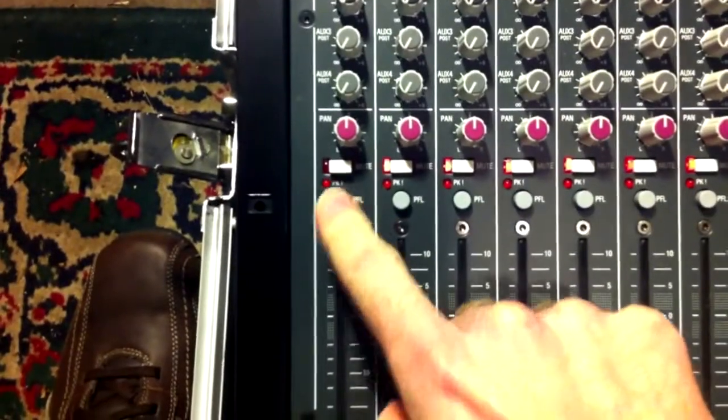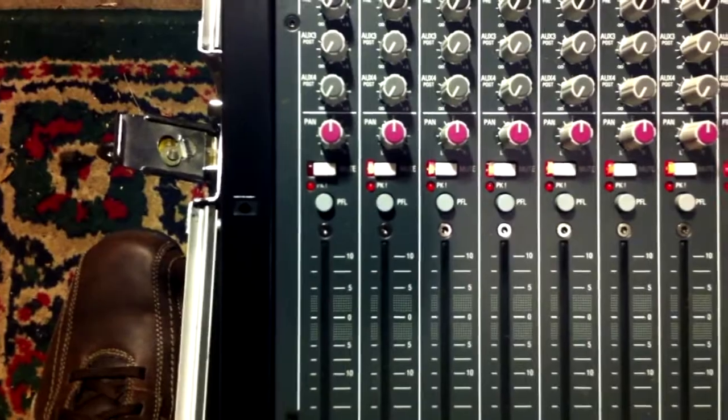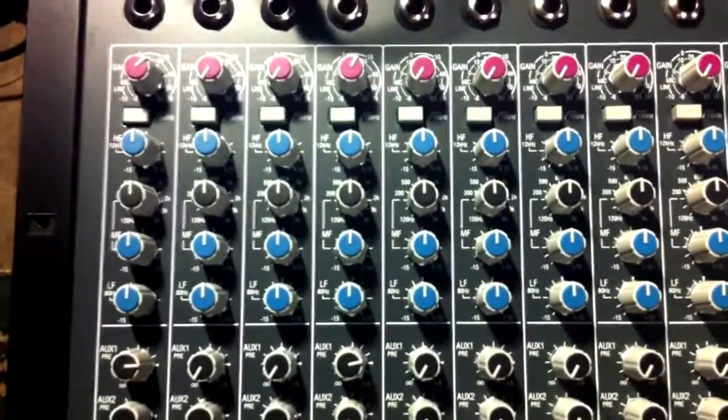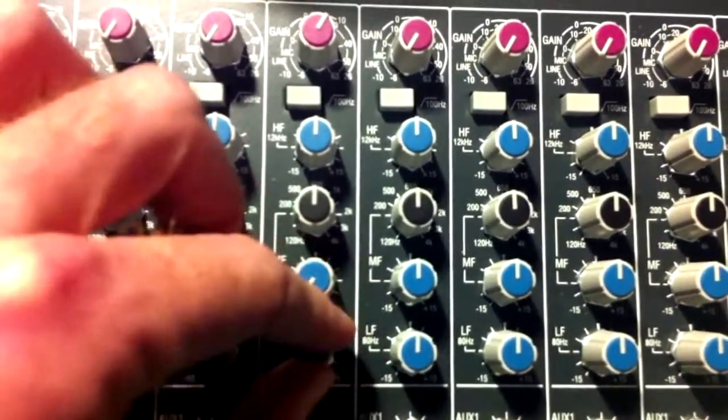Now when we've turned all of our PFLs off, the signal that is sent to the meter will be our main left and right. This is true for most mixers. Now we'll go over the EQ section. So in order to show you how this works, I decided to plug my mic into channel 4, and we'll mess with these controls to see what it does.